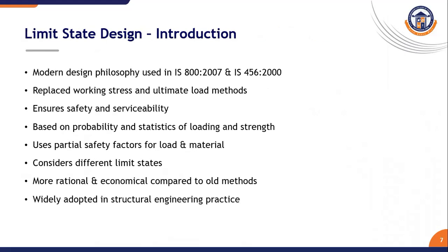Limit state design concept. Finally, let us discuss the limit state design method, which is followed in IS 800-2007. This modern design philosophy ensures both safety and serviceability throughout the structural life. It uses partial safety factors for the load and material to account for uncertainties in design.